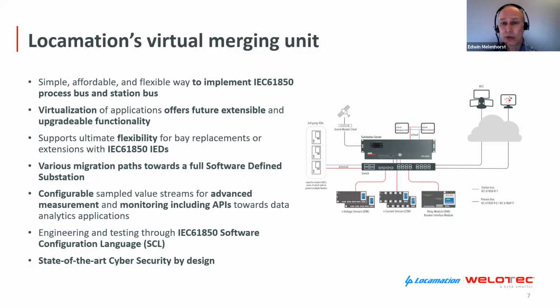The sampled value streams are configurable for advanced measurement and monitoring, including mainstream APIs towards data analytics applications, for example, through a REST API. Engineering and testing can be done through the IEC 61850 system configuration language, also known as SCL. And we implement state-of-the-art cybersecurity by design, which is based on, amongst others, the ENCS security requirements.